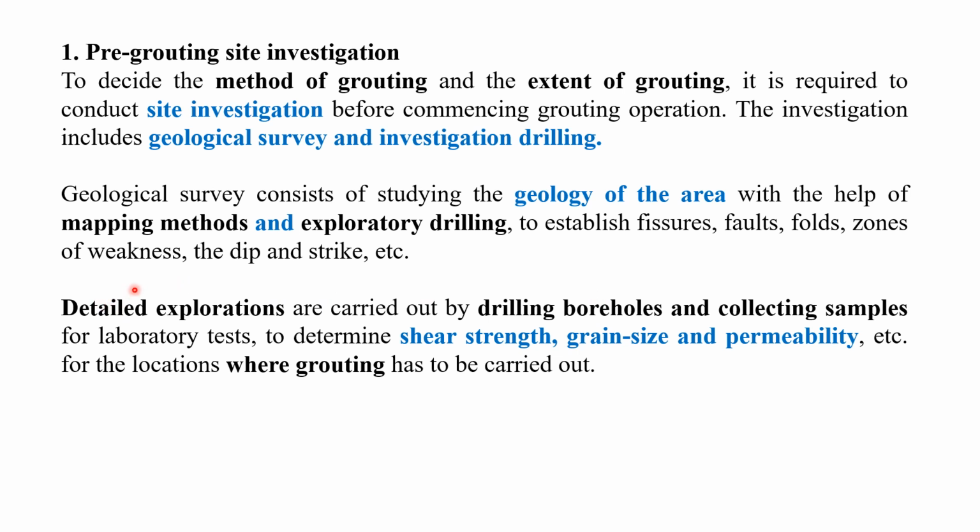And next, the detailed explorations are carried out by drilling boreholes and collecting samples for laboratory tests to determine shear strength, grain size analysis, permeability for the location where grouting has to be carried out. As I told you, we have to go for the grouting either for seepage control or to increase the strength of the soil.